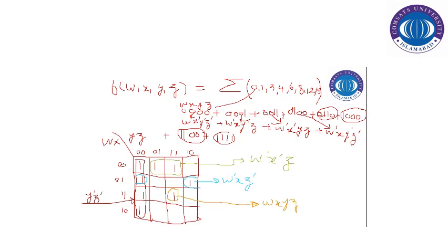So what we've got is the expression here in a sum of products format. We've got these 4 terms, and now we can easily implement those 4 terms in a sum of products format, and we can see that the terms are much more simplified and literals are also minimized for each term, and so the resources are optimized here.